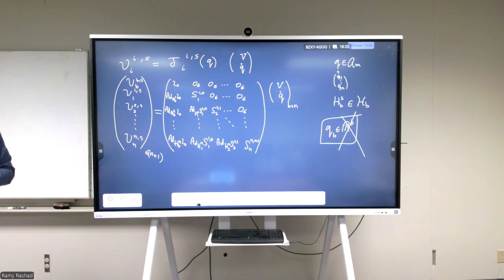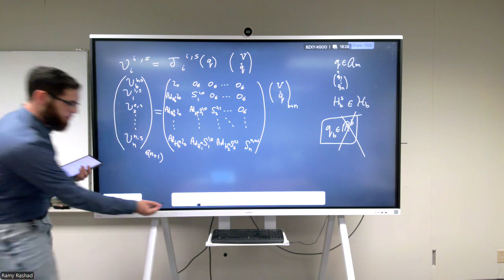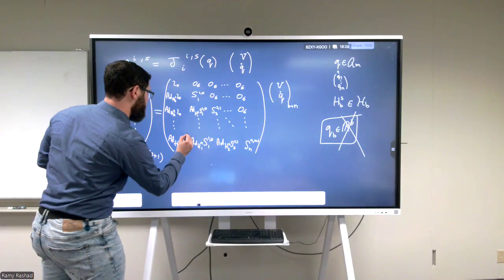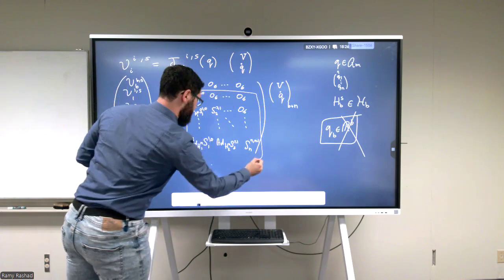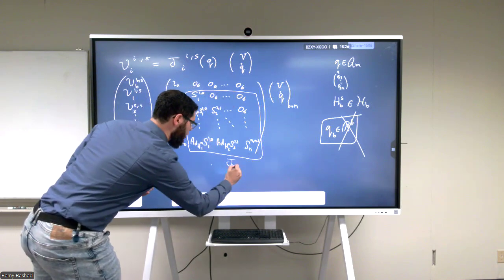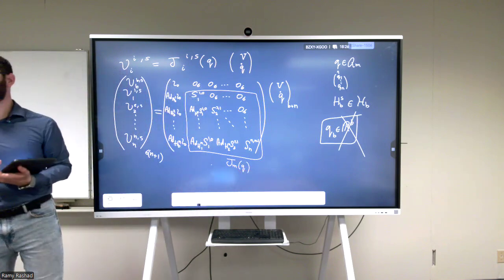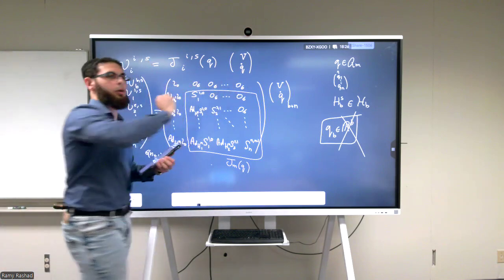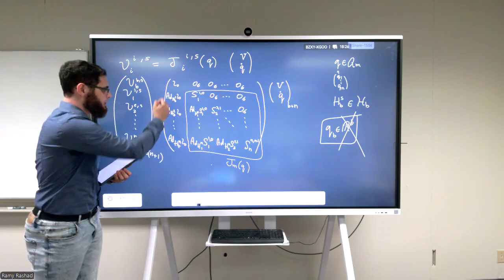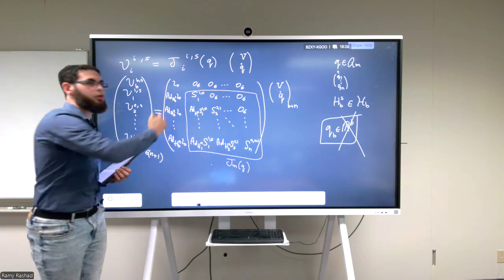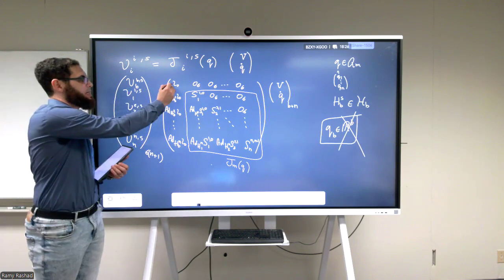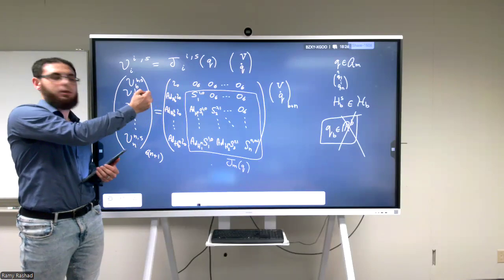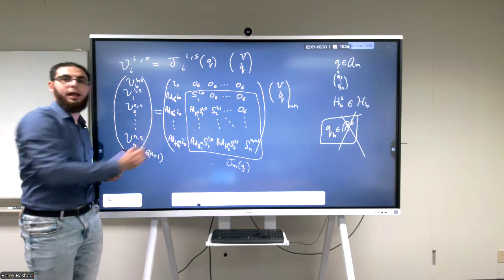It's ugly, but you've seen most of it before. All of this part is exactly the same Jacobian as for a manipulator before. Exactly the same. We added zeros on the top, and this is the only thing that changes here, you see? All of this is due to the effect of the base. And the only thing that we have here is the iota, for the first one, and then iota from B to 1, iota from B to 2, iota from B to N.